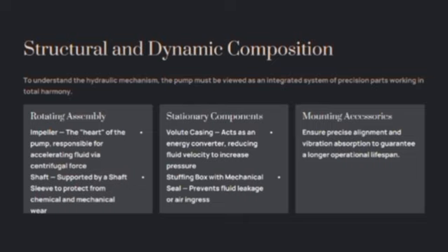Structural and dynamic components. To understand the hydraulic mechanism, the pump must be viewed as an integrated system of precision parts working in total harmony. First, the rotating assembly, including the impeller. It's the heart of the pump, responsible for accelerating fluid via centrifugal force, and the shaft, which is supported by a shaft sleeve to protect from chemical and mechanical wear.